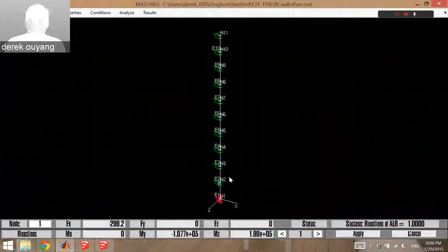So notice this, its shear is exactly the same as what it was before. That's what it's telling me here, like that 300, right? So it's still this 150, 150. Its moment is also exactly the same as it said here, but it has this twist, right? It has this twist, which was the 0 value from before. And technically, so you do have to do some calculations on what this means, because this twist gives you a little bit of extra shear to take care of or to consider, and a little bit of extra moment.